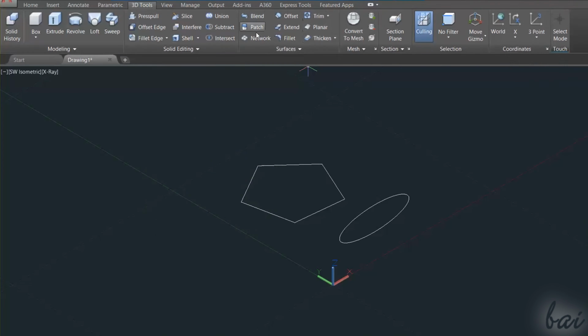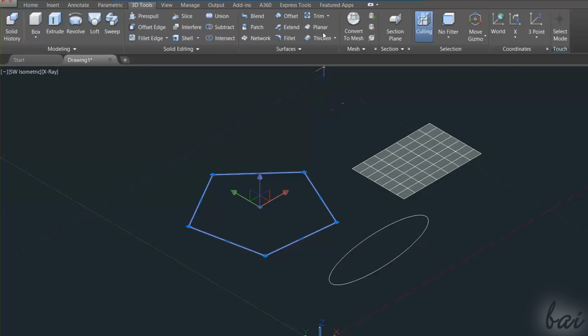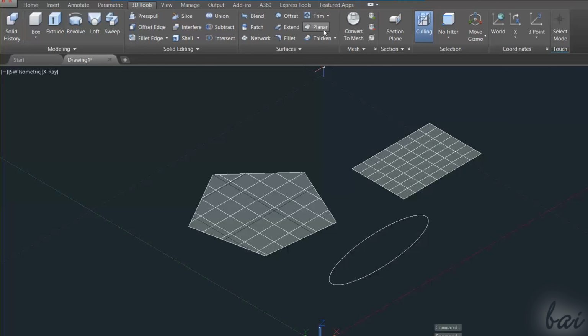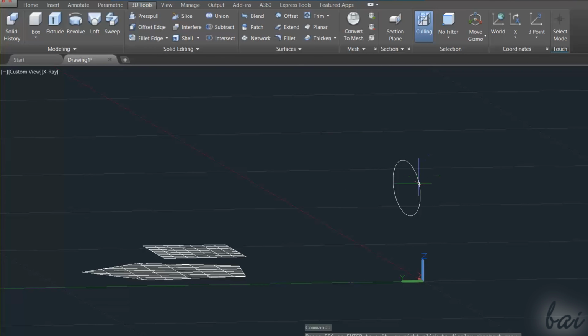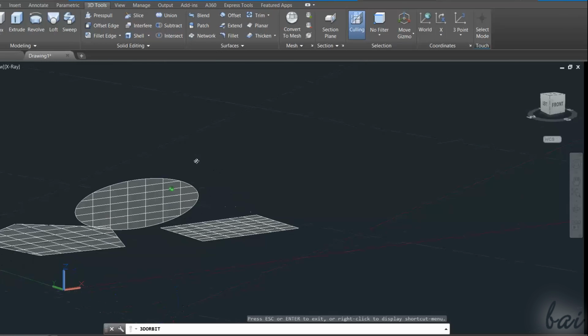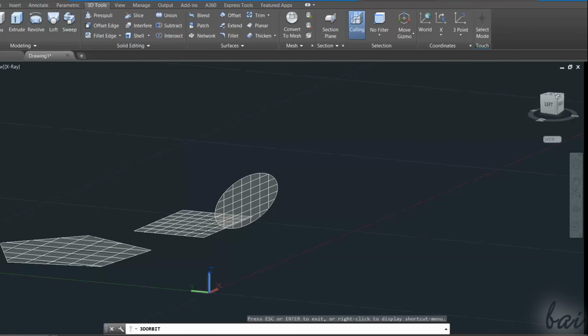To drop planar surfaces with any shape, you have to use the Planar Surface tool. If you fix 2 points on your workspace, you will create a simple rectangular surface as you do with a rectangle tool. If you want to create a planar surface with a customized shape, just apply the planar tool on an enclosed 2D path selected. This also works on shapes that are not parallel to the ground plane of the gizmo system.